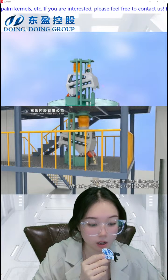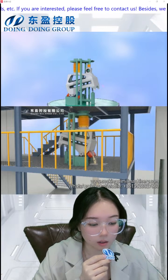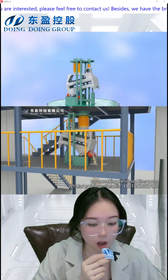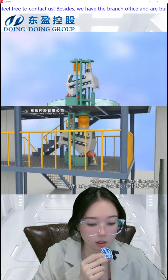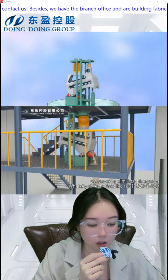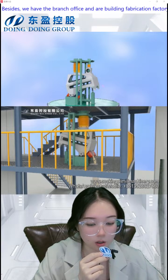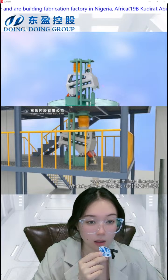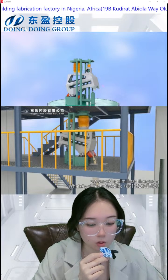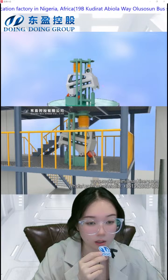For the shell stripping machine, based on the porosity of the material, we usually choose a disc shell stripping machine, which uses the friction between the surfaces of two grinding discs, a fixed disc and a moving disc, to squeeze and crush the oil seeds.